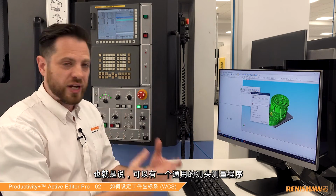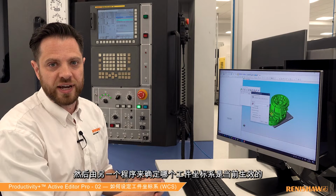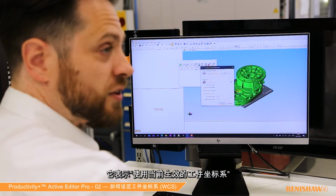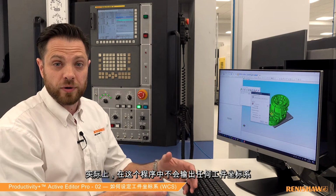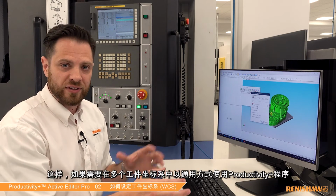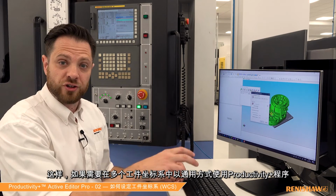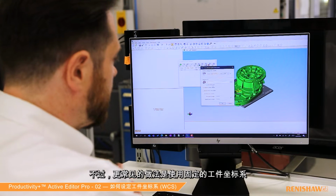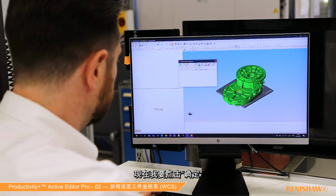That means you can have a generic probing program and allow a different program to determine which work coordinate system is active. If you want to do that, you can flick this switch here that says Use Active Work Coordinate System. That means we will not output the G54 in this program. We will not output any work coordinate system in the program. We'll allow a main program to determine that. That's how we can get around that situation where you want to use the Productivity Plus program in a generic way across multiple work offsets. More commonly though, we are going to be working in a fixed work offset, so we can leave it as that, and I'm going to hit OK.